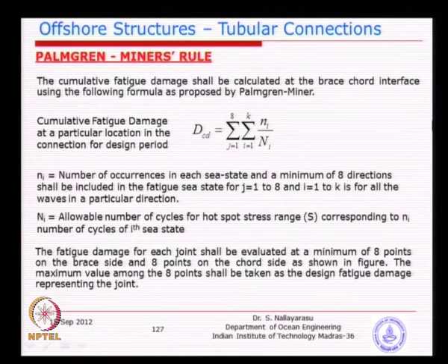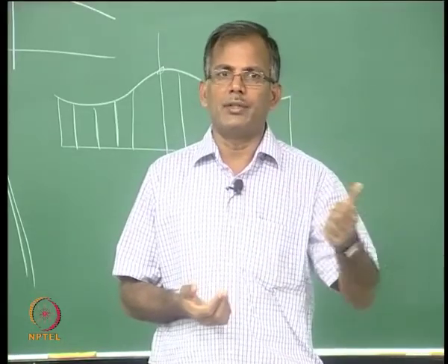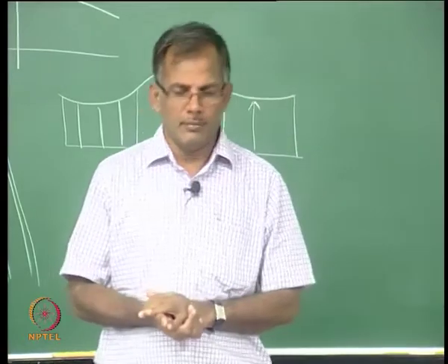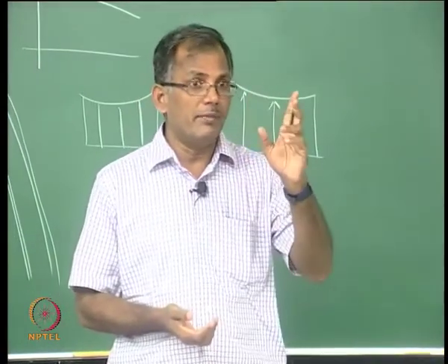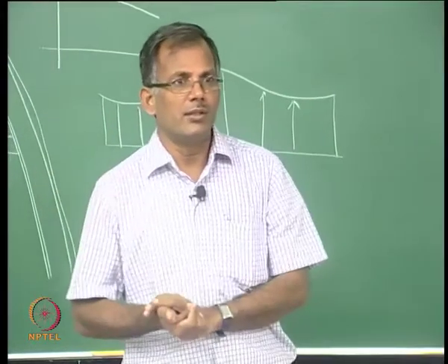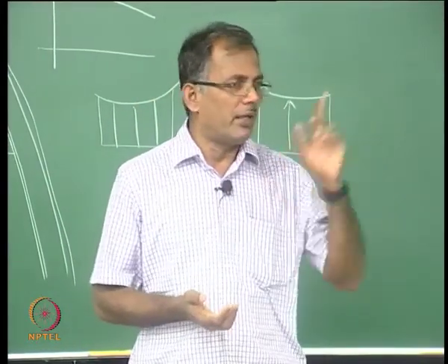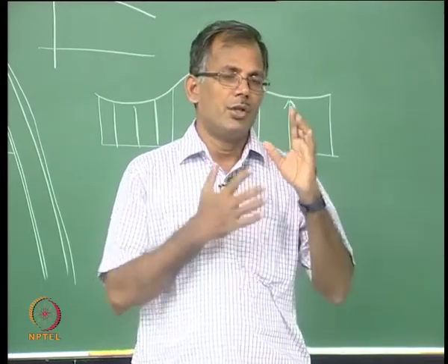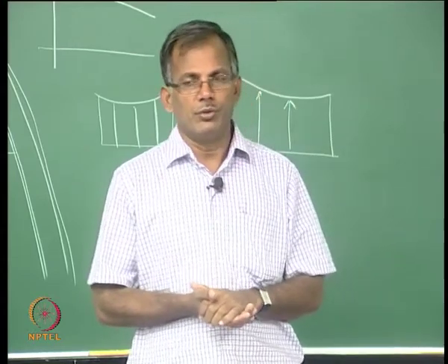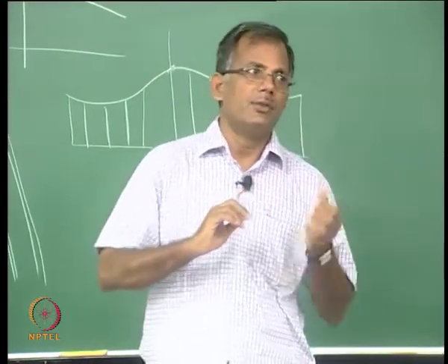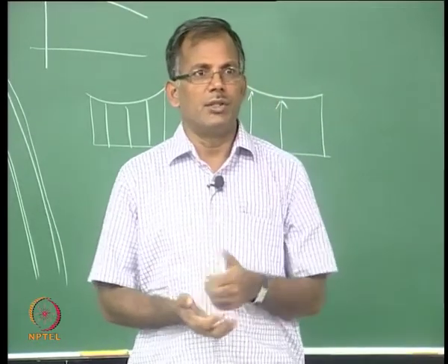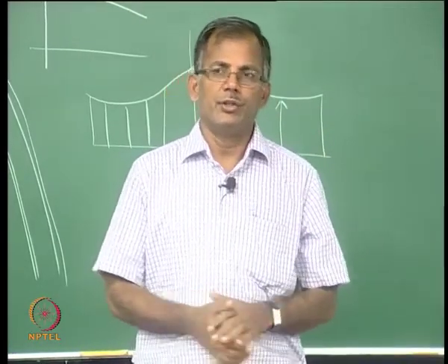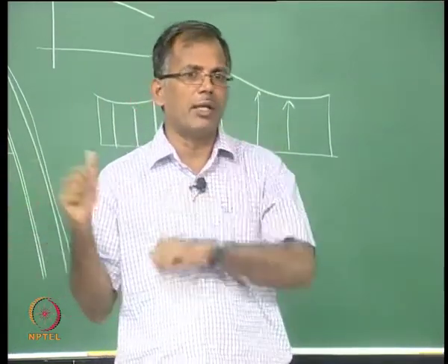So, how do we get the calculations for the fatigue damage? We have come up with the steps now. In the last 4 classes we have been discussing fatigue, starting with crack propagation theory and basically Paris law of crack growth, the relationship between crack growth and the material constant or material toughness, and then we learned about the so-called stress concentration factor, for which a typical equation from Efthymiou was shown to you, with calculation at 8 points. So, stress concentration factor multiplied by nominal stress gives you the stress range. Then you go to the SN curve to read the number of cycles to failure.